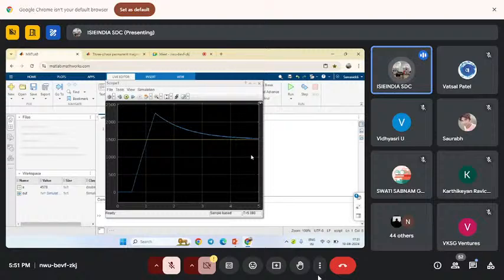It was taking 4 seconds to reach 1527 rpm. In control systems we study rise time, overshoot, and settling time, and you can see those in the graph. Here 0.5 to 1.2 is the rise time, and this is the overshoot. This is because the speed is over the desired speed, and after some time the speed is reducing and stability is reached. So this should be happening here. Simulation, when you open this one.